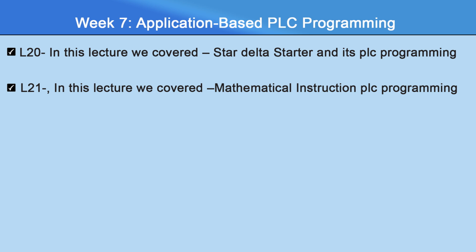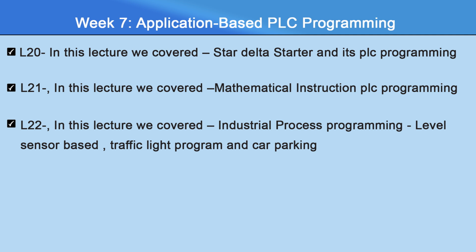In lecture number 21 we covered the mathematical instructions, which cover the add operation, subtract operations, multiply operations, and in lecture number 22 we covered the industrial process programming based on the level sensor or traffic light based programs, and we also saw the car parking programming. So we can say that in week 7 we shifted our focus to practical real world applications of PLC programming.